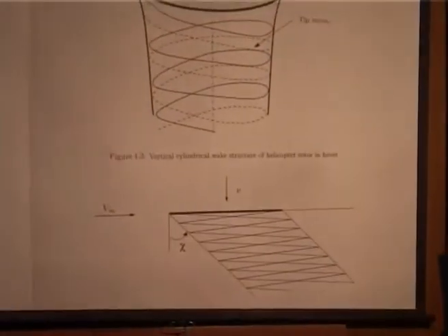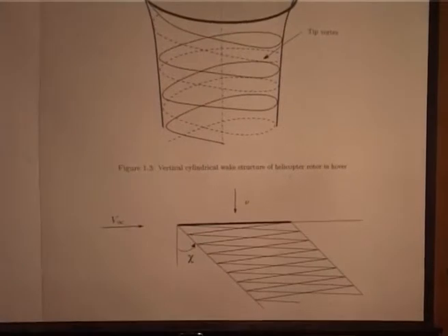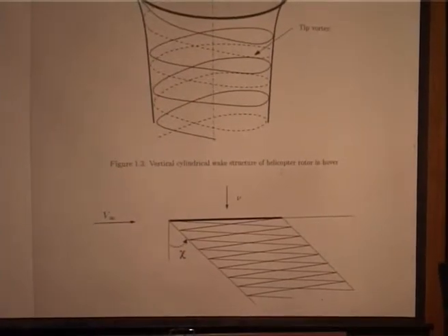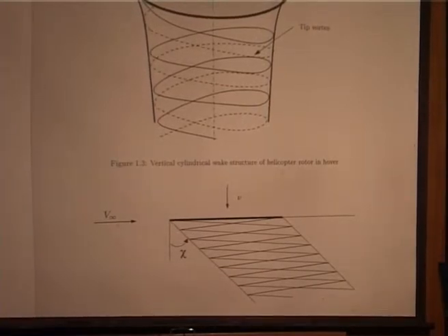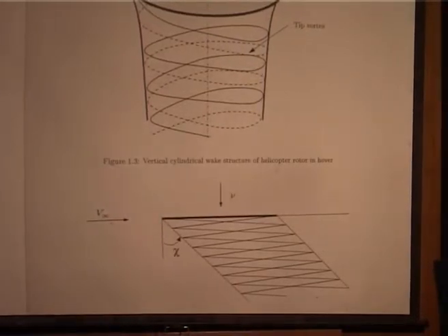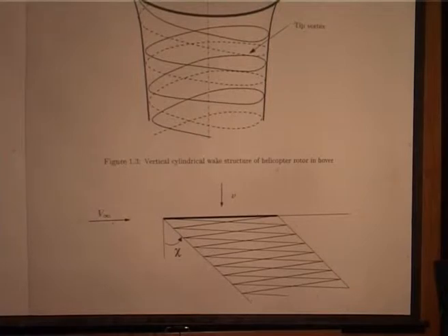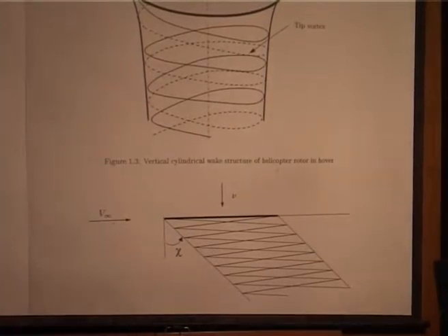Okay. If you go around advance ratio 0.1, then that angle is close to around 60 degrees. So, in the range of 0 to 60, that is the transition. In the sense the wake is not completely swept behind the rotor disc, it is not straight below also, but it is very close to that, and then it is skewed.